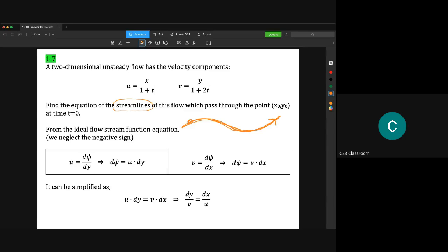As I told you previously, we could compare the experimental work for streamlines with the calculation work. The experimental work can be done using a wind tunnel and a smoke generator. However, if we have a moving fluid, it is not easy to show it as a line unless you use ink in a water tunnel, for example, or a smoke generator in a wind tunnel.